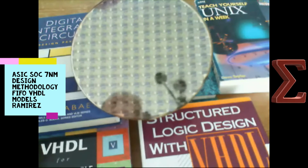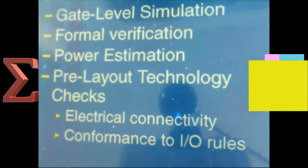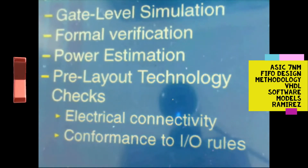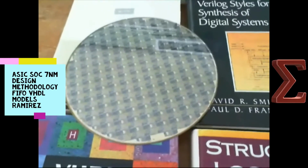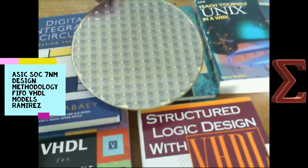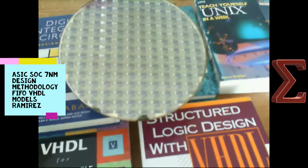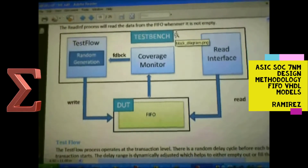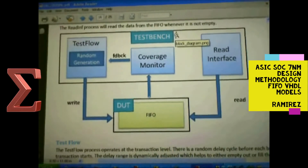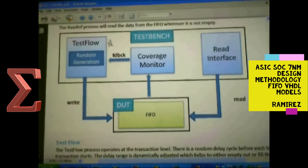Then I emphasize some functionality in terms of functional simulation and verification. So the RTL is tested for functionality and correctness of the design, and simulation involves event and cycle-based simulation. This takes place while assertion-based verification is used to verify functionality and correctness of the design.